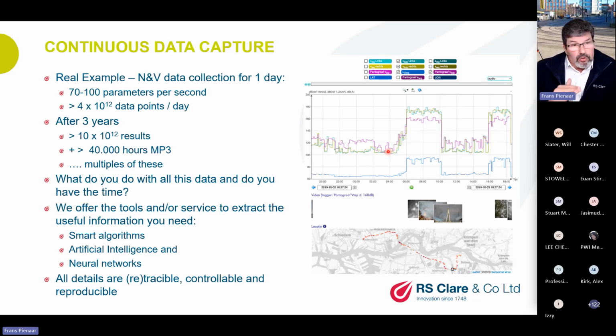You need to do a little bit of tweaking, because all networks will be different. It will depend on the wheel sizes, the wheel profiles, the rail profiles. All of those things will play a role in what frequencies will come up. We and our partners will then work with you to get specific readings, so you can have the right information to do a root cause analysis.